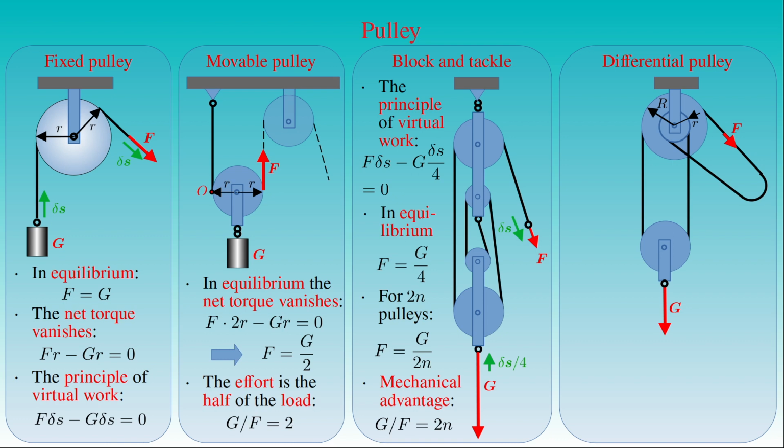The fixed pulleys are toothed to avoid slippage of the chain. If the load G is applied on the movable pulley, it is also exerted on both sides of the loop. As a result, the forces F and G over 2 are applied with the lever arms R on the fixed pulleys, turning them clockwise, and at the same time the force G over 2 is applied on the pulley of radius r, turning it counterclockwise.